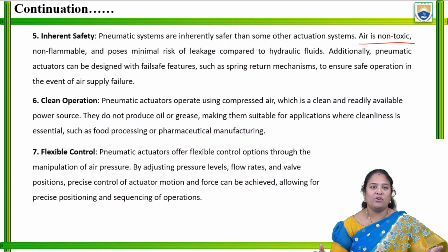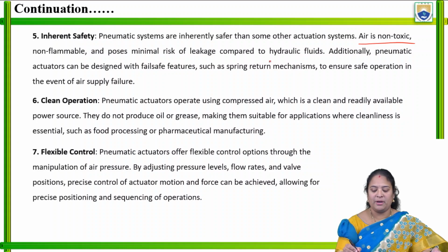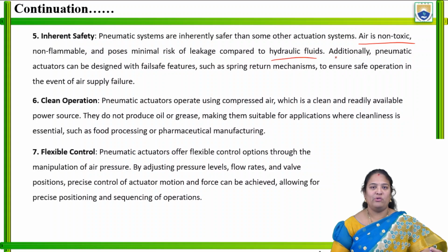If there is any sort of leakage problem with oil, what happens? There will be some risk. Since we are using air in this type of actuator, and the air is non-toxic and non-flammable, there will be a minimal risk from leakage compared to hydraulic fluid. So this is one of the advantages of the pneumatic actuator, that is, inherent safety.